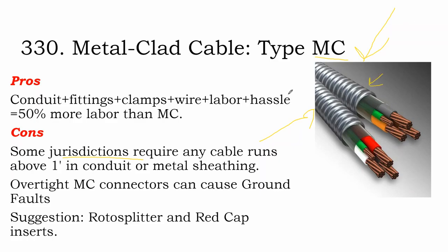But I think for solar, having this metal is, hey, none of the other power lines in your house are in metal, and the utility feeder entrance conductors inside your house don't even need to be in metal, and they're at a much higher power capacity. I think that this metal protection is really for critters, so that they don't chew up your power lines, and I think that can make sense.